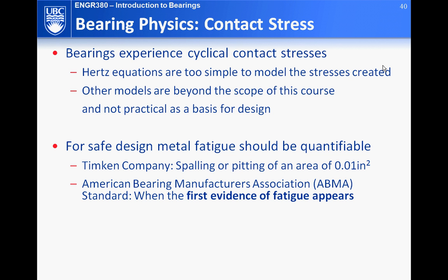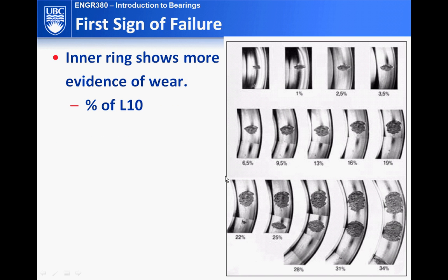However, you also need to understand this: even though the bearing develops this kind of chip or spalling, that doesn't mean the bearing will stop working right away. It will probably still work and can still provide good functionality, but in terms of the standard, you would call that fatigue failure.